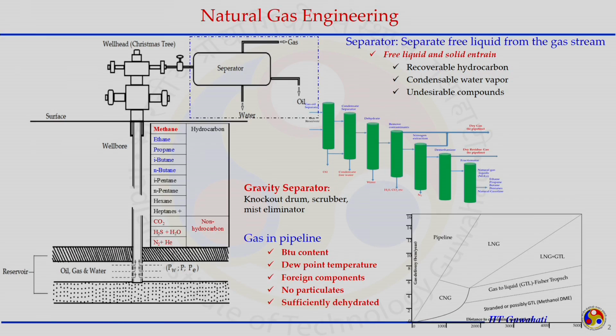Now, today's lecture will be dedicated to understanding how a separator does its job, how to select an appropriate separator, and the other accessories related to the separator will be discussed. In this lecture, we will also understand how to choose an appropriate separator. So, the separator shown here is for separating three phases: water, gas and oil.